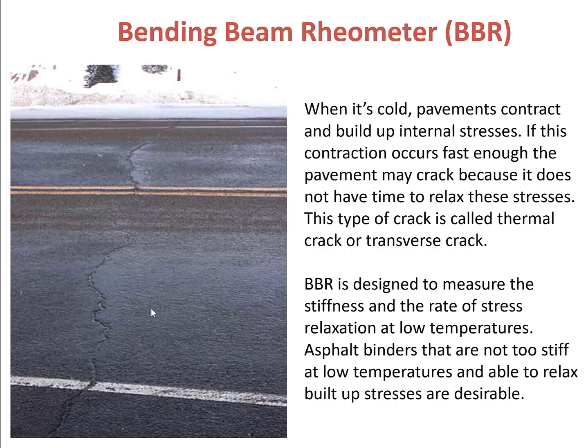The BBR test is designed to measure the stiffness and the rate of stress relaxation at low temperatures. These parameters are important indicators of the asphalt binder's ability to resist low temperature cracking.